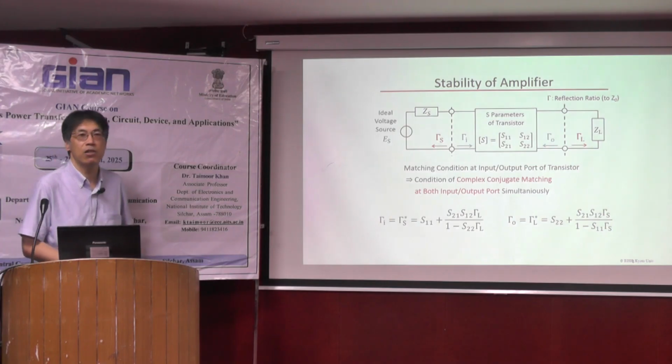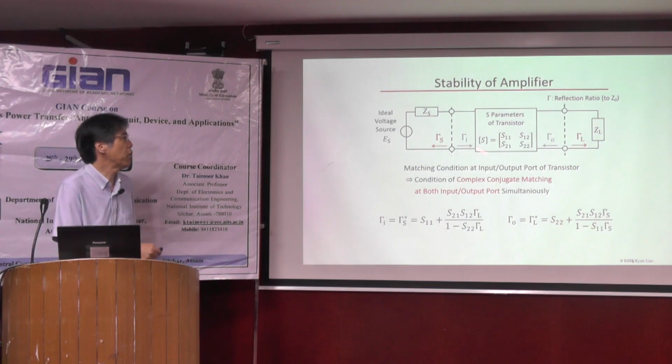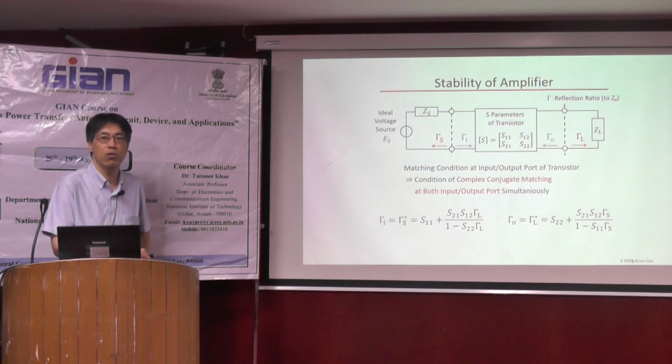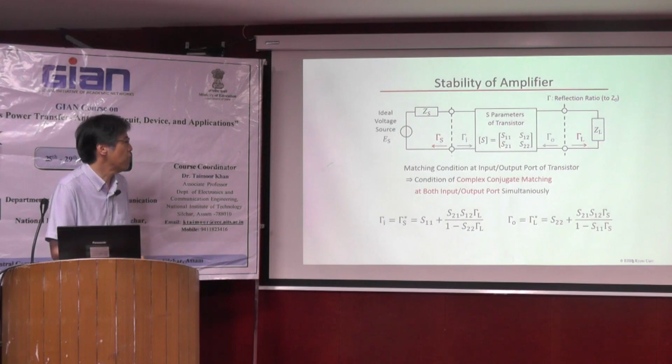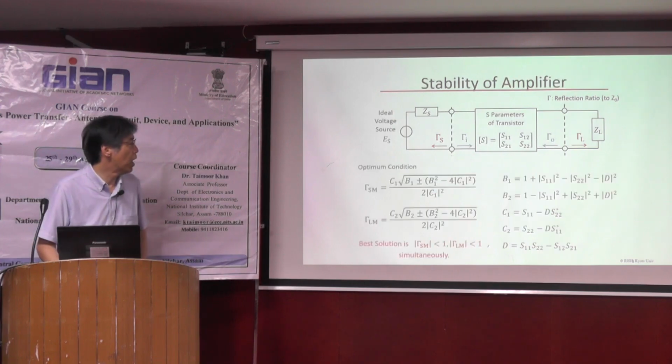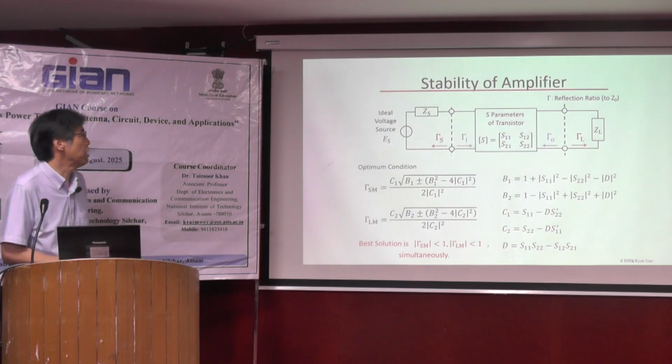You've already run S parameter, scattering parameter S. And when we measure the S parameter of the transistor, FET, HBT, etc., with help of this S parameter, we can calculate the integrated impedance here. And with help of this parameter, we can estimate the stability of the amplifier.